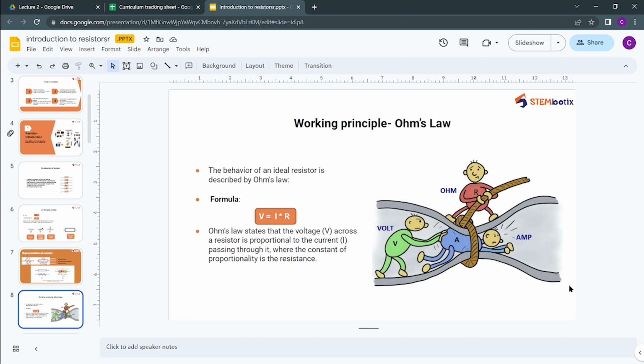The name potentiometer comes from its function as an adjustable voltage divider to provide a variable potential at the terminal connected to the tapping point. Now at the tapping point the value of voltage varies according to the variation in the resistance value. So it is also called a potentiometer. Volume control in audio devices is a common application of potentiometer. So these potentiometers are used in volume control knobs in audio devices.